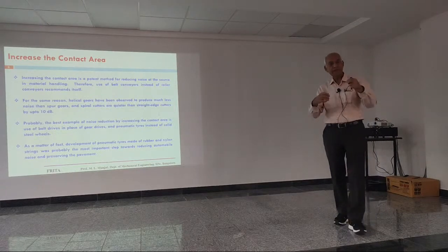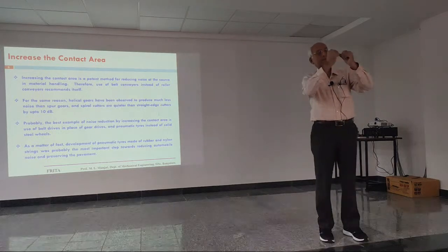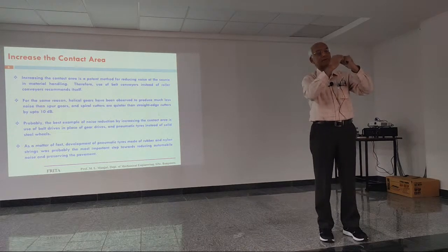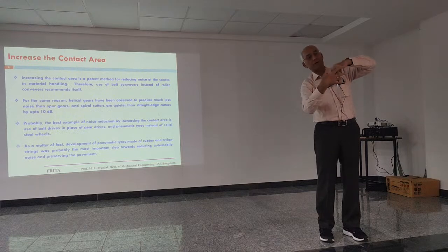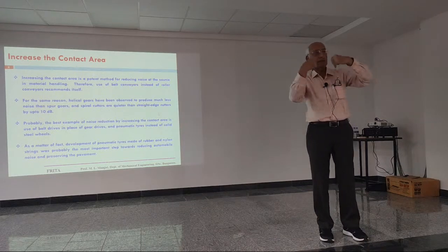So you can see in a spur gear, the contact is just like this. So it's only this much. But in helical gears, the contact goes like this. So the contact area is much more than in spur gears.